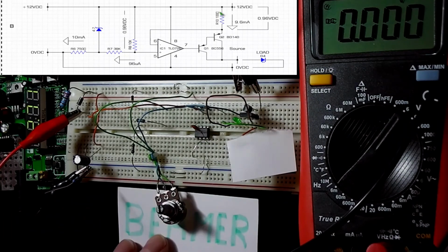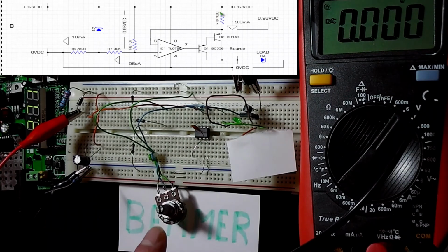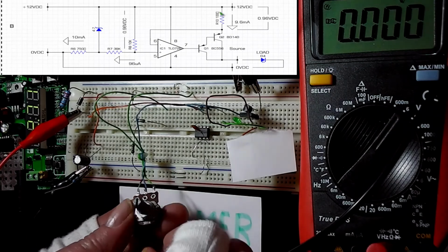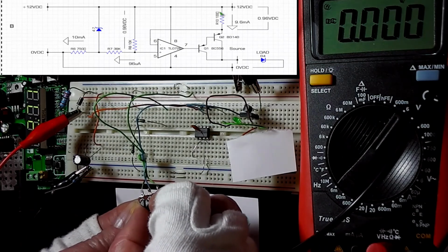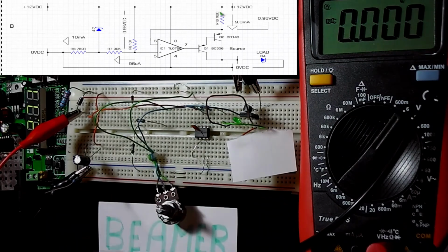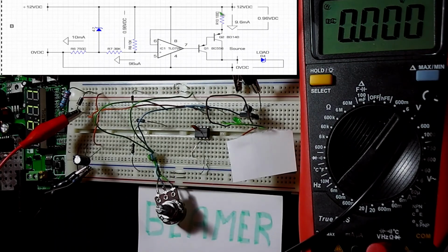That suddenly dropped out, and I'm not fully down on the potentiometer. And just to demonstrate that, let's see how much to go. Wow, I would say it's about a quarter of a turn. So there is a dropout before the potentiometer gets to a quarter of a turn towards the compliance voltage.